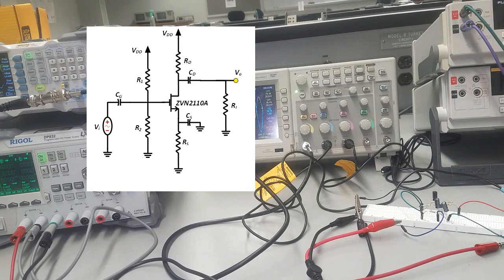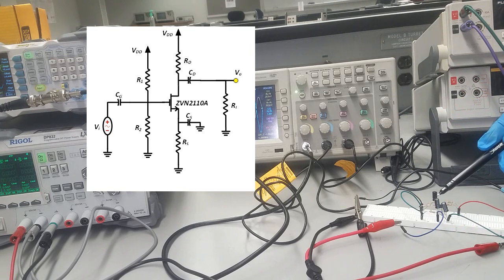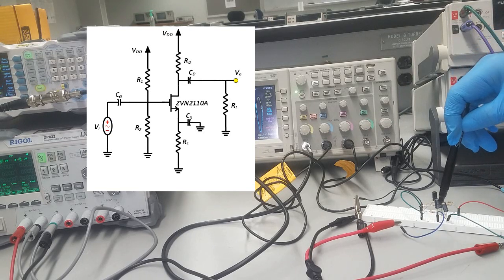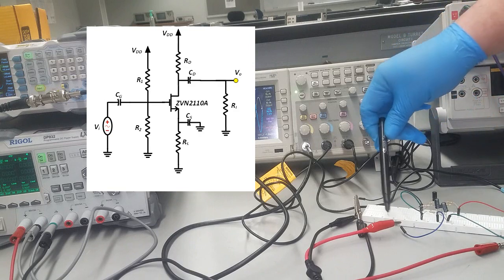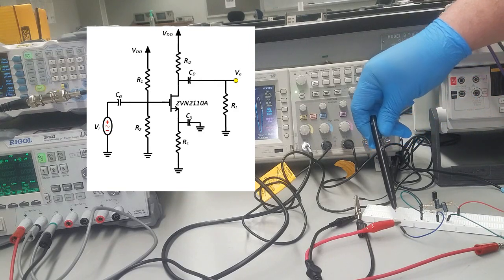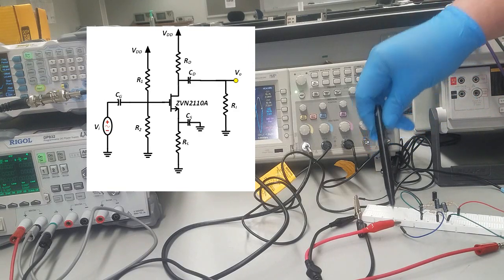Now keep in mind that when you connect the capacitors, those are electrolytic capacitors, so the polarities need to be well investigated. So the polarities for the capacitor at the gate should be that the negative polarity is at the signal generator. The reason is the voltage at the gate is roughly around 5 volts, 4.7 volts. So the voltage at the signal generator is roughly 0, so it's more negative at the input of the function generator.